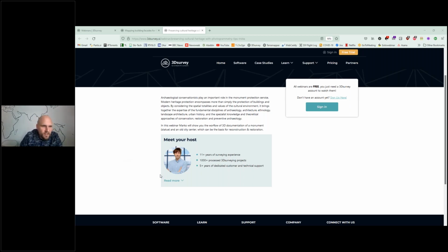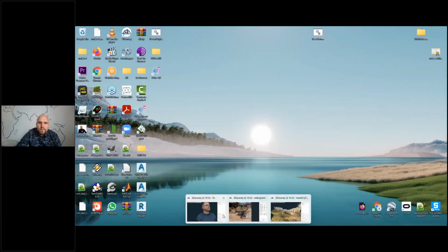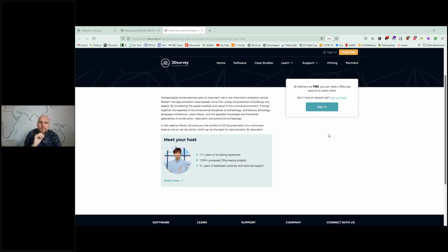Now, Mr. Nunez is asking again, in the house reconstruction project, when you took some videos with the phone, did you also record the GCPs that were located on the grass? Maybe I can help you a bit with this one. So what was actually done in this project, we combined drone images with phone images, so with the phone frames, and actually we placed the ground control point targets on the grass, on the road, I think approximately 5 targets, and we use them for orientation, of course, but mostly for the drone images, and then all frames from the phone were orientated with help of the drone images.